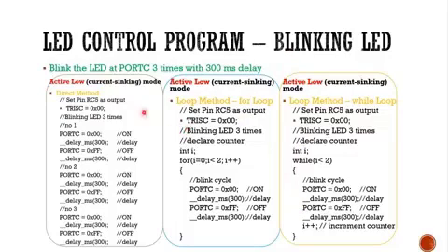But before you write to the port, make sure that here TRIS must be set as output. So the first thing before using a port, you need to configure TRIS.